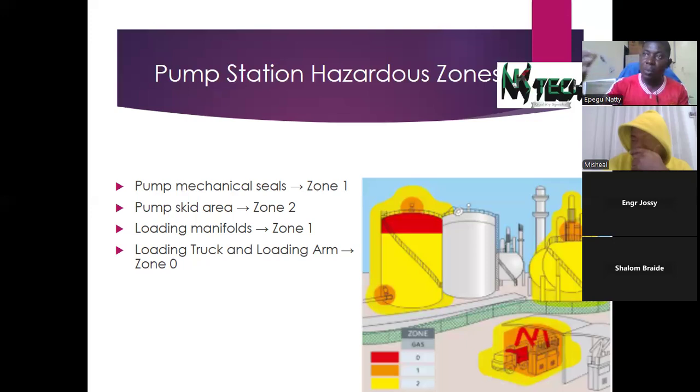While we know that the vapors, if there's any leak in this region, have a flash point of about 150 degrees. So if there is a leak and the temperature of this pump is about 300 degrees, it means there's going to be a fire and an accident. So there's no way the management will not listen to you. In fact, they will even applaud you.